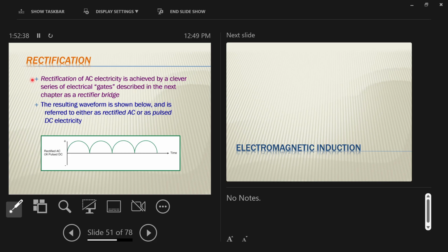If you turn this device on, operating at half-wave rectification, for 1 second, it's going to be able to deliver as much power as a non-rectified AC device would be able to for half of a second. Said in another way, you're making half as much power here. Half the time you're not doing anything, right? If you turn it on for 1 second, it's only actually making power for 0.5 seconds, because between every pulse is an equal amount of space of nothingness, okay?